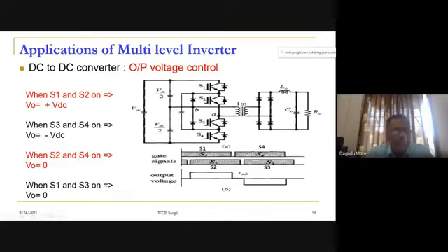So here, whatever DC voltage we are getting, it may be in kV. We have seen that it is 100 kV or 50 kV, 80 kV, and current may be less, hardly 1 ampere, 2 ampere. One such application is an ESP, electrostatic precipitator, used in thermal power plants for air pollution control.